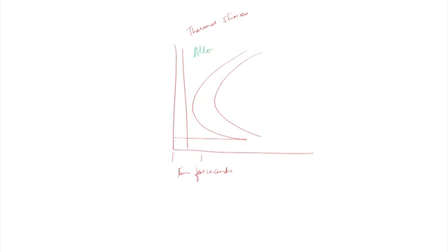So, what will happen because of that? When I add an alloying element, this curve shifts towards the right. So, it will go somewhere like this. Now I am giving enough time for having a martensitic transformation. So, now I can have much slower cooling and still I will be able to get martensite, because I am able to skip the nose. By doing that, I am reducing the thermal stresses. So, that is the idea of adding alloying elements in steel.